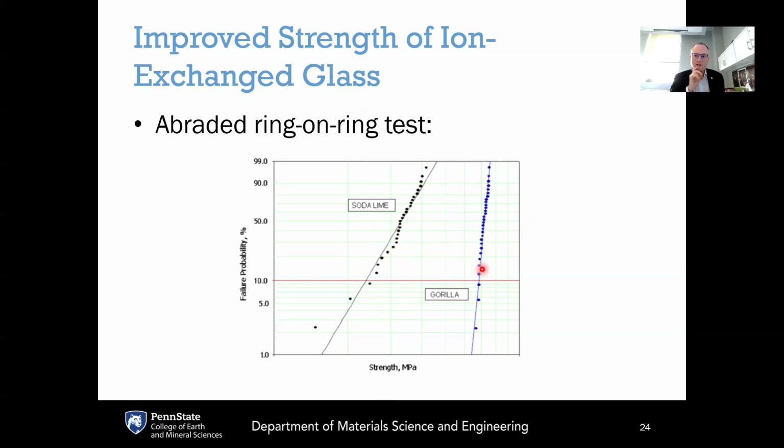With an aluminosilicate glass, there is a strong glass network, but at the same time, the sodium ions are not forming non-bridging oxygens. Instead, the sodium ions are providing charge compensation for the alumina units. And this means that they're not tightly bonded to the glass network, which means that the alkali ions are highly mobile, at the same time as providing a strong glass network. And as a result, Gorilla Glass is much more effective at ion exchange compared to soda lime, so that the overall strength is significantly higher.